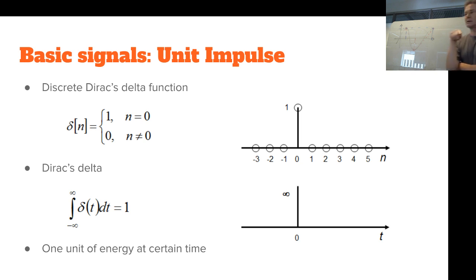The same way, for the analog systems, you have this step function that you put into the system to see what the step response of the analog system is. Then you can compare it by measuring it with an oscilloscope, and then you can go back and try to figure out what the transfer function of the system is.